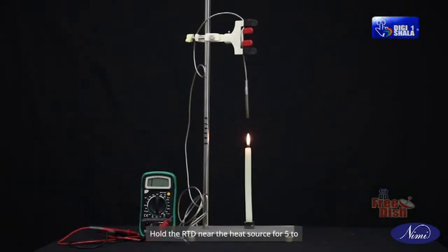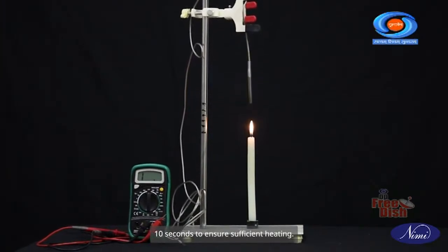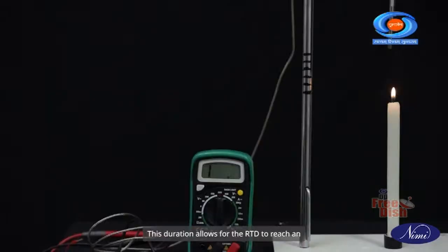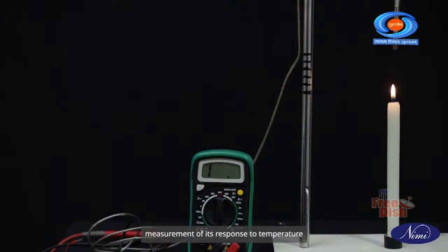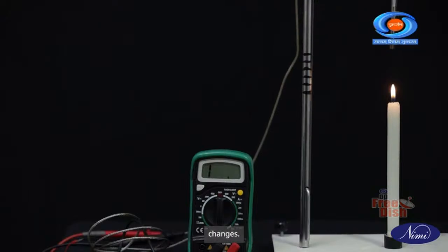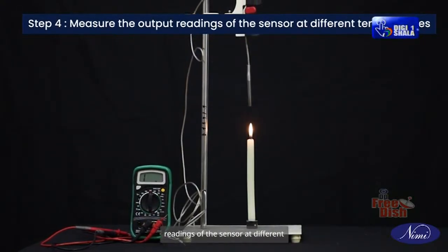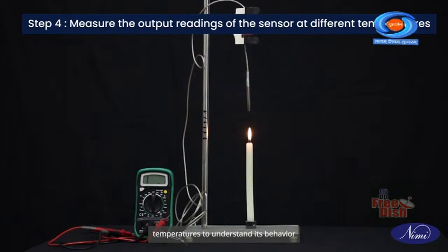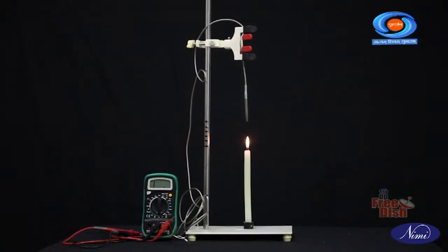Hold the RTD near the heat source for 5 to 10 seconds to ensure sufficient heating. This duration allows for the RTD to reach an equilibrium temperature, enabling accurate measurement of its response to temperature changes. Next, we will proceed to measure the output readings of the sensor at different temperatures to understand its behavior under varying thermal conditions.